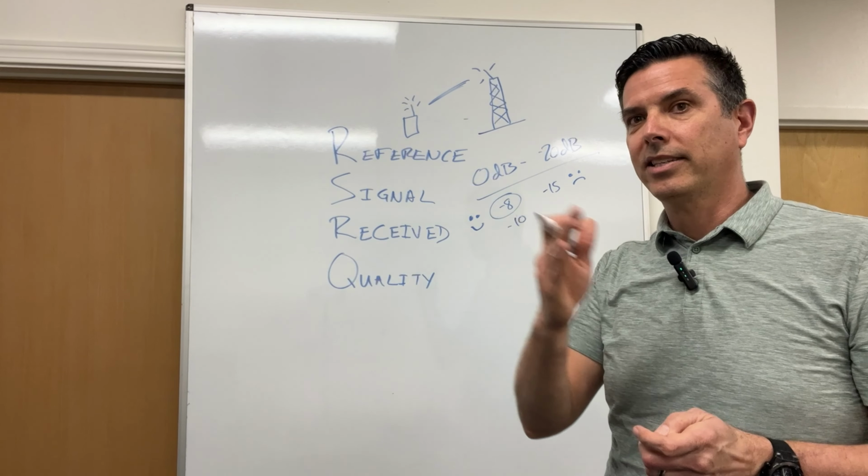If you're using, let's say, a radio signal inside the building to generate signal into your DAS, and that radio is putting out a PCI of, say, 261, and you're doing your walk testing, you want to see that PCI 261. If you have multiple zones in a large hospital or stadium DAS, an airport DAS, and you have the operators, your mobile operators, AT&T, Verizon, T-Mobile, if they're all giving you multiple radios, they all have a specific PCI that goes into a specific zone.